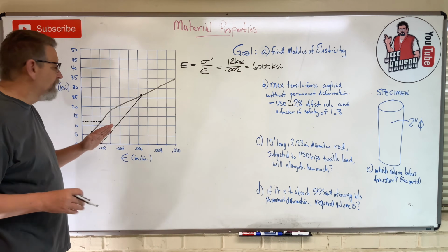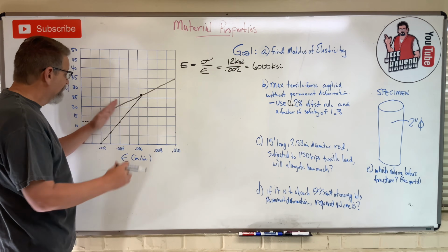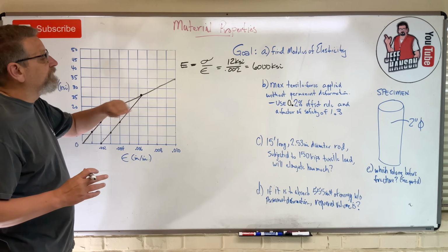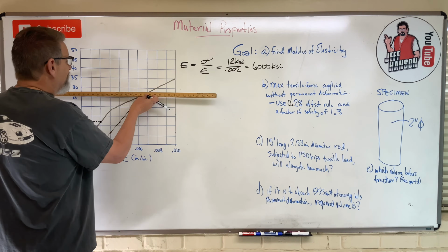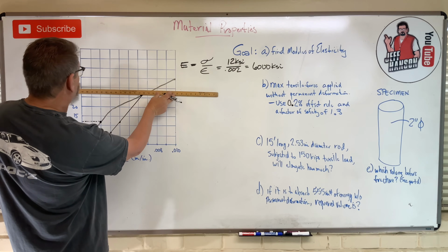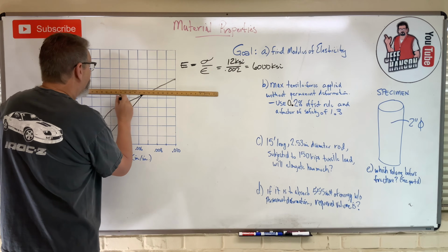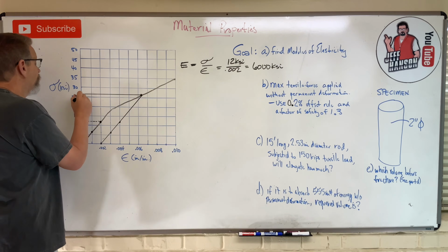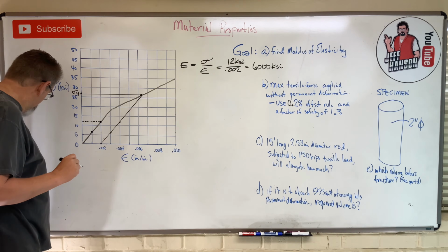We talked about this in the video, that some industries, instead of using a 0.2%, will use a 0.1%, really, and tighten that up. But most of us, for these kind of materials, we just use the 0.2%. Now, what do you do for that? You take that and you read that across, okay? So let's read that across. Let's get it as straight as we possibly can here, okay? And that will give us our new yield strength. That's sigma y, sigma yield, okay?